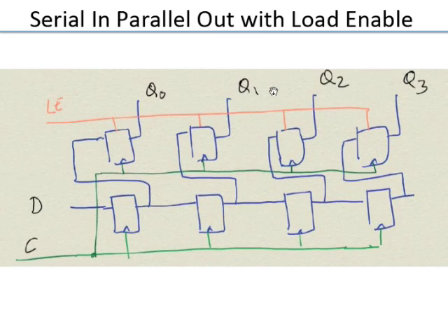So you do this only if you're concerned about power, or maybe there are certain other reasons. For example, you're controlling some circuitry out here, and for Q0 to Q3 there are only certain bit patterns which are valid to that control circuit. While you're going from one valid pattern to another, when you do the serial shifting, you go through a lot of intermediate states which are not valid states, or which will put whatever you are doing into a wrong state. Then you will be in trouble.